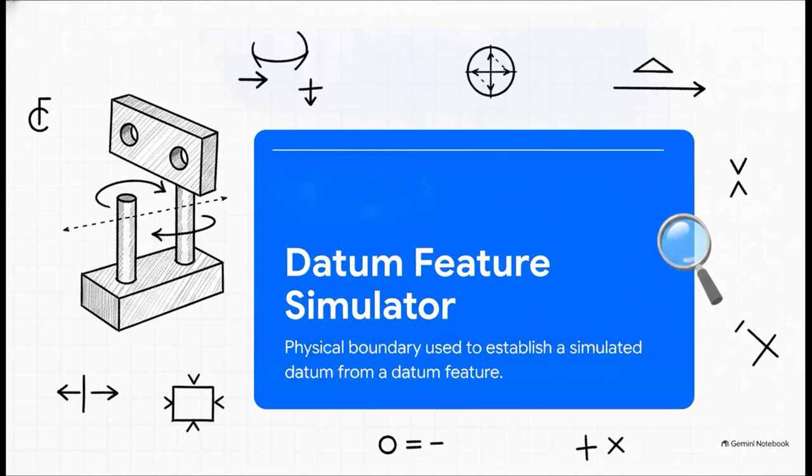Look, drawing perfect circles in CAD is a breeze, right? But out in the real world, how do our inspection tools actually figure out where the center of a multi-feature pattern is when the physical holes are imperfect? Well, the standard defines what's called a datum feature simulator. Since datums are theoretically perfect, we need a physical stand-in for that perfection, like a flawless set of gauge pins on a fixture block. Those pins act as the simulator to engage our imperfect datum holes, which locks down the rotational constraint and establishes our true center axis.